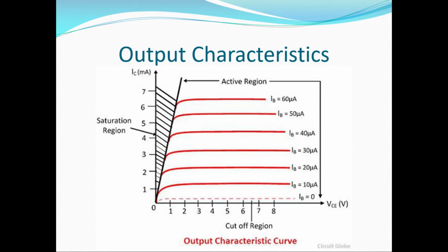From the above circuit arrangement, we can also determine the output characteristics of an NPN transistor. Figure shows typical output characteristics of an NPN transistor. They relate the output current IC to the voltage between the collector and emitter VCE for various values of input current IB. Note that the quantities VCE, IC and IB are all positive for an NPN transistor. If the transistor is PNP type, we reverse the terminals of the batteries VCC and VBB so that VCE, IC and IB become negative.